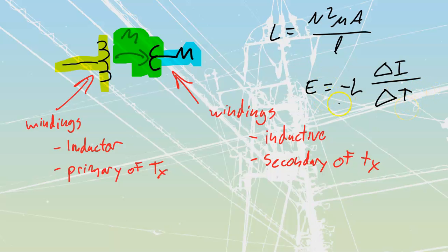This one here is going to be my counter EMF, and it talks about the way that we build up voltage inside of a coil. That's this L over here, which represents this coil, so the L transfers down to here. Anytime that we've got changing current over changing time, which is going to be an AC sine wave, changing current, changing time. Maximum change over here, minimum change over here, insofar as my current goes. We're talking about the change, not the absolute magnitude. We're going to need to use that one to deal with a bunch of our counter EMF that we are going to have inside of here.